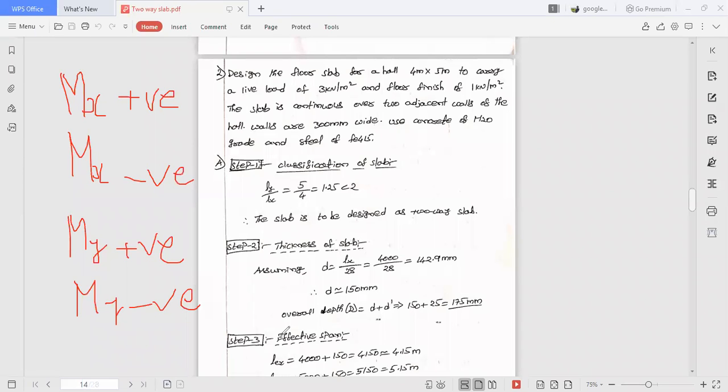One is torsion design step will be added, and in addition to 2 reinforcement, we have to calculate 4 reinforcement in total. So the problem will become somewhat lengthy compared to simply supported slab. So let us understand step by step, and remaining 80% of the procedure is same. So let us just discuss in detail. And where we will provide all these reinforcement, let us see.